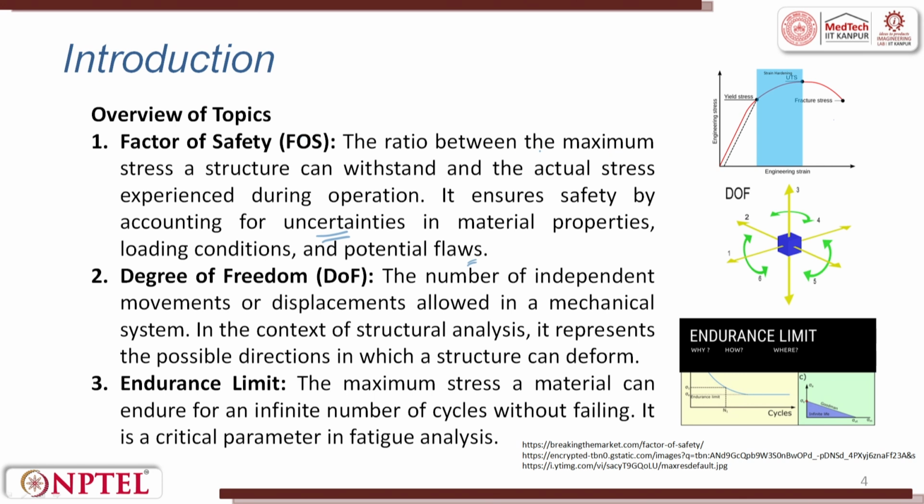So, it is the ratio between the maximum stress a structure can withstand and the actual stress experienced during operation. If you see here the engineering stress strain graph, you can see here yield, then the ultimate, then a fracture, right. So, now you should make sure that between here and here the factor of safety takes care.